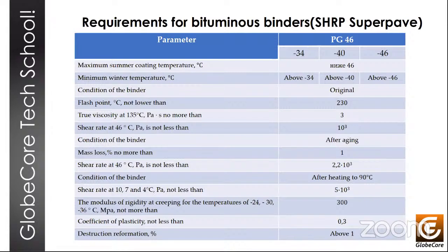So the designation of the binder grade, for example, you can see something like PG 82-34, means that it should work well at a high temperature of the pavement, up to 82 degrees centigrade, and at low temperatures down to minus 34 centigrade. So this is what those numbers stand for. And in the PG 46-34 zone, respectively, at temperatures of plus 46 and minus 34 C. And between these two extremities, according to the operating conditions of bitumen in the layer, there are another 35 zones